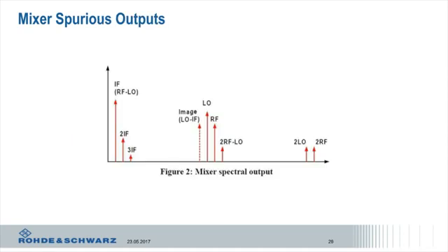Okay, so what does this look like? Again, this is a plot of it, looking in the frequency domain. You'll see I have an RF in the middle, and an LO. If I want to get down to an IF, which is on the left there, RF minus LO is the common thing for a receiver. I want RF minus LO to get to this IF frequency that I can process, but I get all this extra stuff.